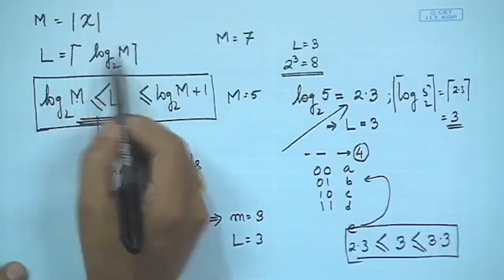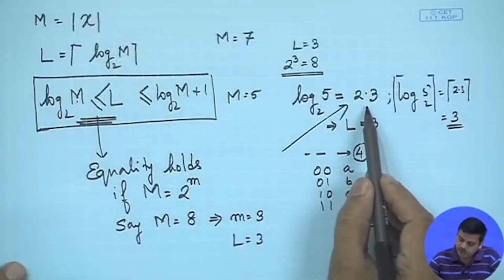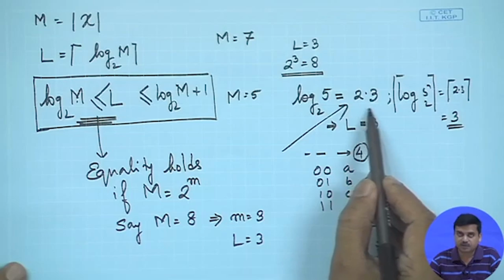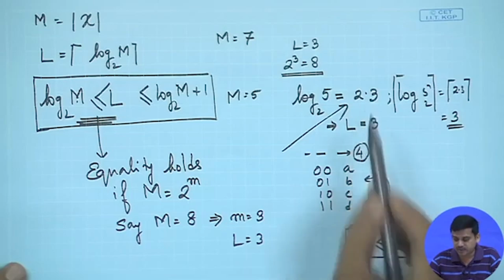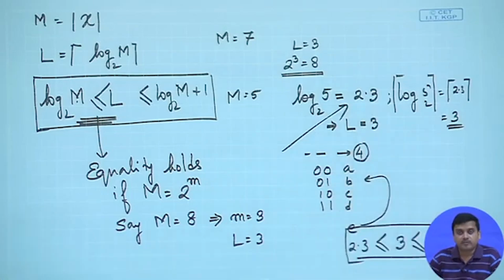If that is not necessarily true, this extra margin, here we have around 0.7 bits roughly, 0.7 bits which are extra per symbol. Now, if we are sending, let us say, 10 to the power of 7 such symbols, that means 0.7 multiplied by 10 to the power of 7. So many extra bits are required to be communicated. So, we will see next if there is a possibility of improving things while using fixed length code.